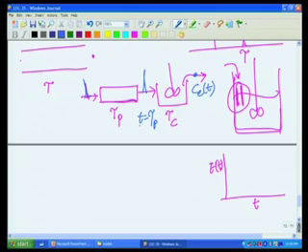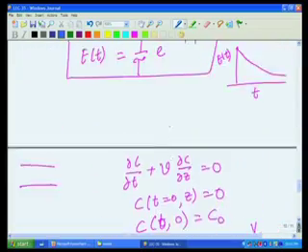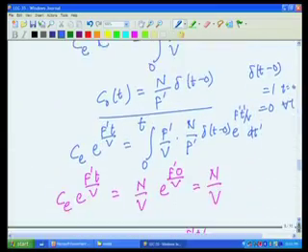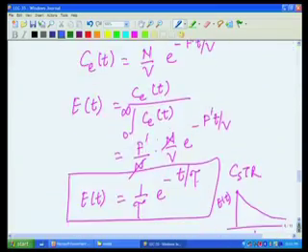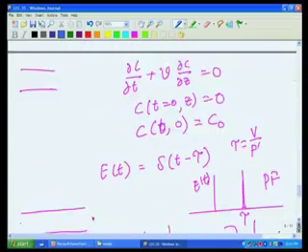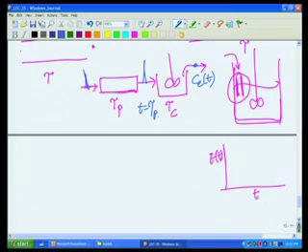So, after time t equal to tau p, this reactor behavior is similar to having a single reactor and the pulse input, which we saw in the previous CSTR example. So, we should expect this response, but not from time 0, but from time t equal to tau p, because till such time has elapsed, we do not expect the tracer to come into the inlet of the CSTR.